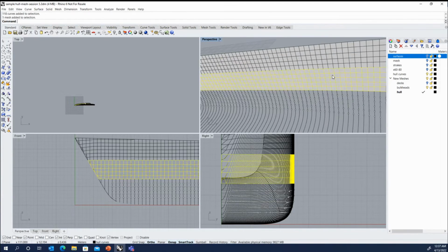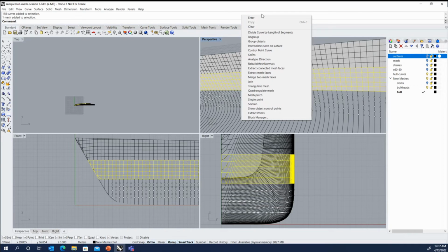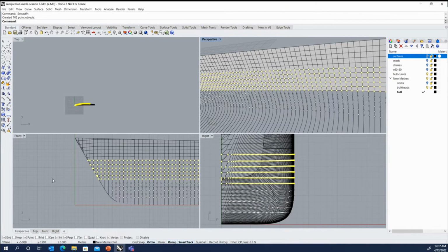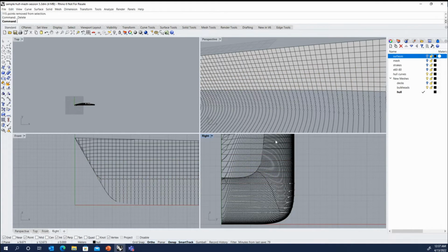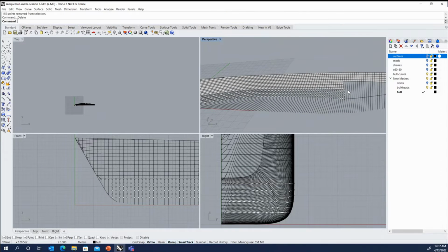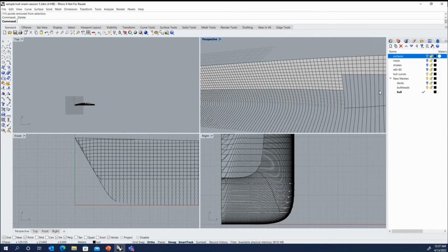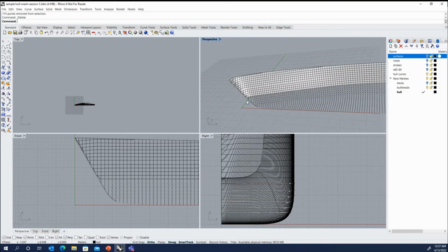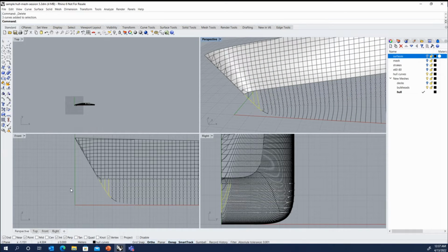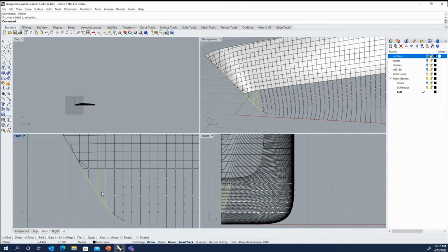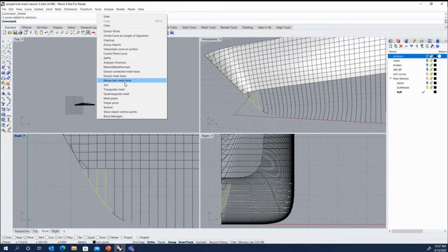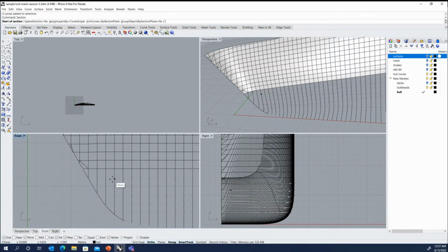We will use extracted nodes from the mesh above. So we'll unselect the bottom row and then delete the rest. It has the same end location, so we don't have to worry about deleting any extras there. For this bow portion, stiffeners are running fairly flat. We'll do the exact same thing we did the last time up above, and we'll use the section command and extend these forward.